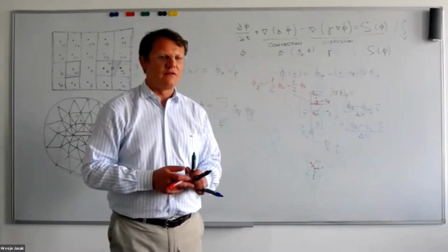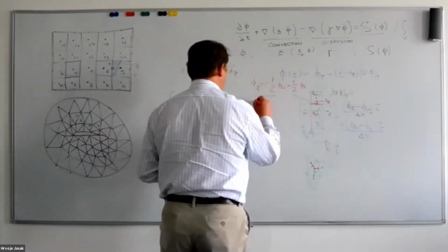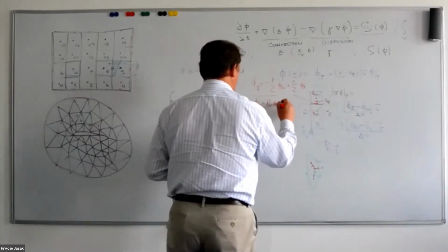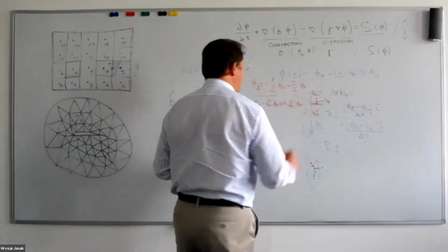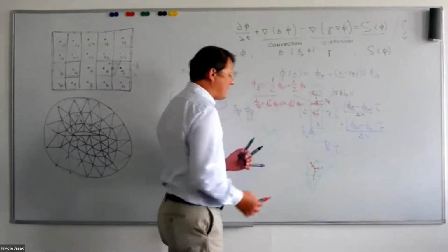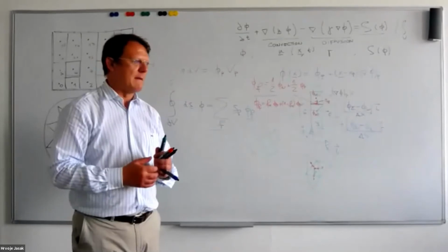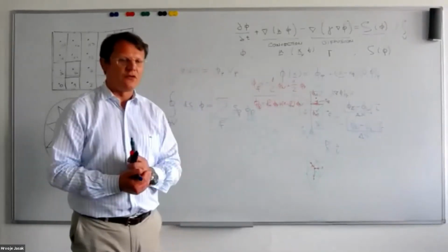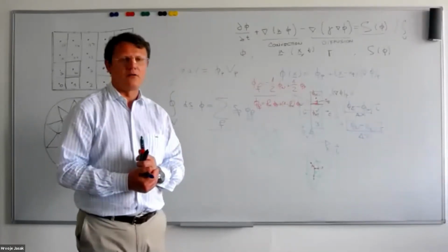On the slide, you have a slightly more general form, which states phi f equals fx phi P plus 1 minus fx phi N, which takes into account the fact that the cells left and right of the interface may not have the same size. Okay, so fx will be the geometric interpolation factor for a linear function between the two values.